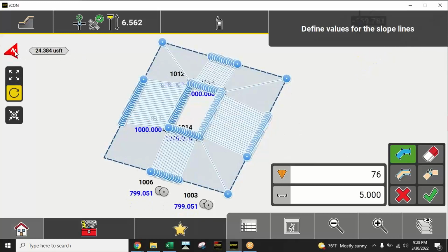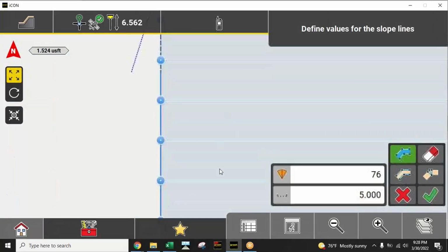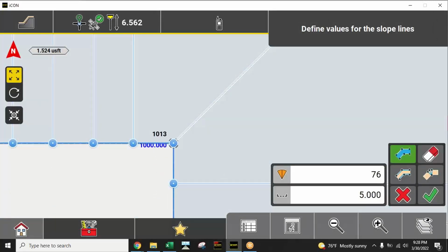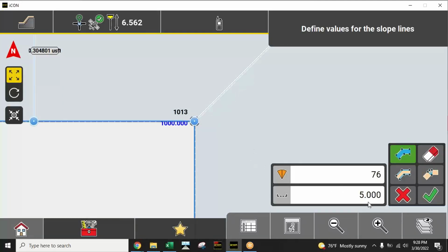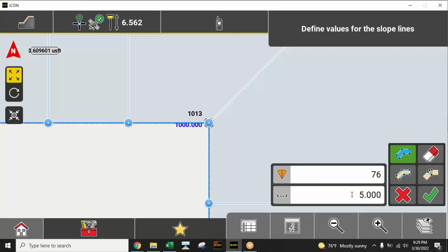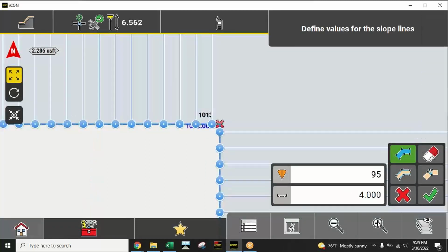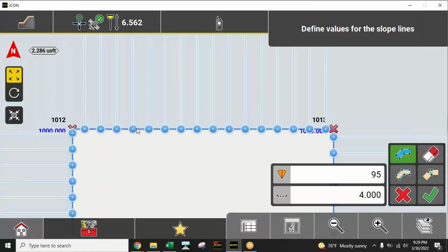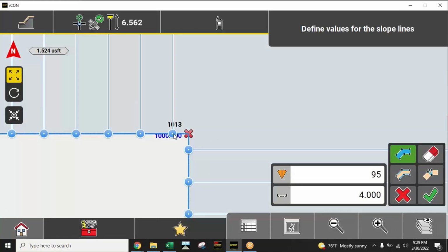I'm going to flip this thing back in plan view here so you can look at it up here on one of these corners. So it puts these points every 5 feet. You know what, I'm going to choose 4 feet just so it makes it a little bit clearer here, because 65 is divisible by 5, but not 4. So it puts your points every 4 feet, but that's not necessarily going to make it land on your corner points here. So you can see it's kicking one off there every 4 feet and going straight out with your